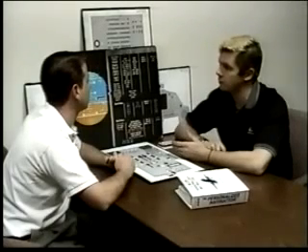You got to remember that that kind of goes against what our profile says in the flight manual. Our profile says that we need to climb out at V2 plus 10. SRS, though, if we got to V2 plus 30, it'll command V2 plus 30. So we need to fly V2 plus 10. The other thing to remember about SRS is that it will never command a level flight. It'll give you at least 120 feet per minute climb.